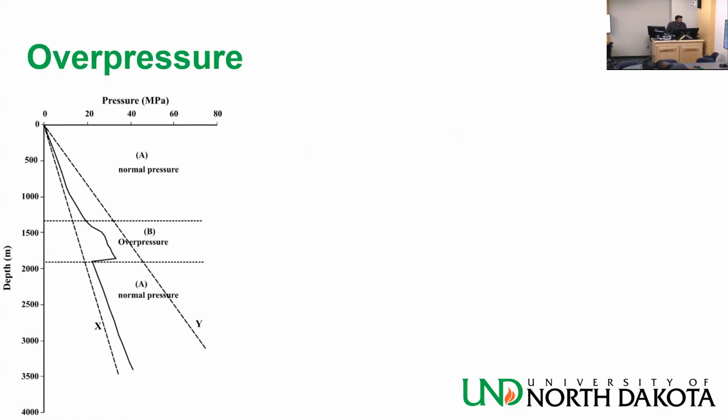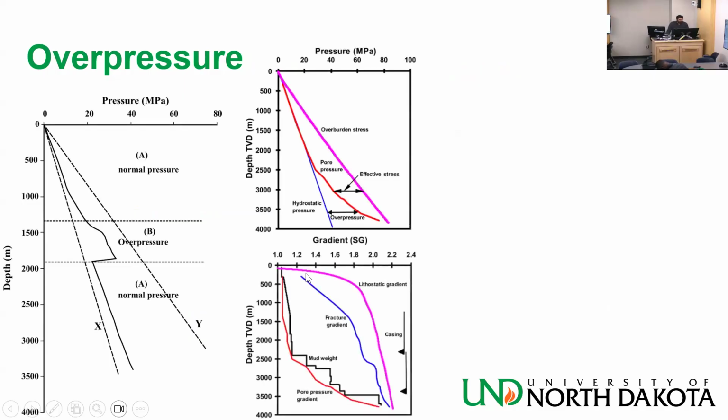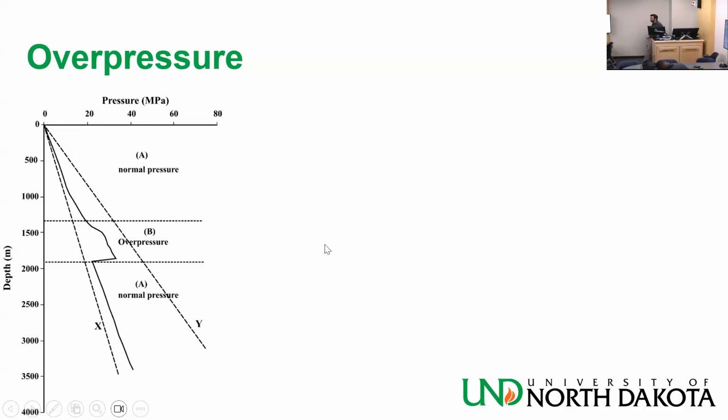Anyway, now, again, I have a pressure traverse diagram. How does the overpressure look? The extra pressure. Is it an increase in the slope or a decrease in the slope? These are straight lines like the ones I drew last time, an orange one and a pink one, remember? And I asked you, which line, X or Y, represents the biggest pressure? That's going to be the Y. Correct? Very nice. Why the Y? Smaller slope, yes. Remember the slope is feet per PSI. So yes, the Y has a smaller slope.